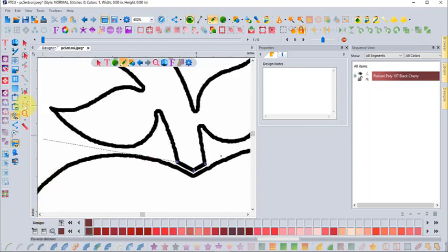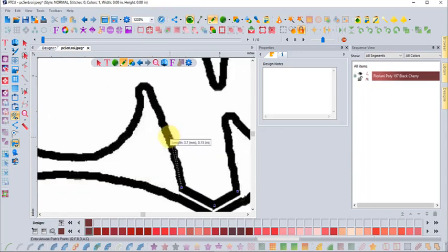But of course, you can use the zoom tools on your workspace to do that. But see how I can zoom in and make my clicks, and see how that feels like a curve. So I'll click here and then hold down control and click there to get that line a little bit curvier. And then here, it's kind of curvy, but if I hold down the control and I make that little click, see how it affects all this?